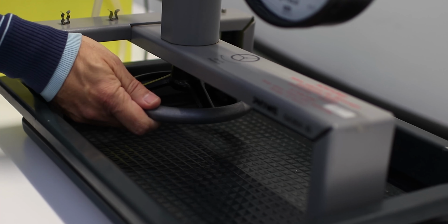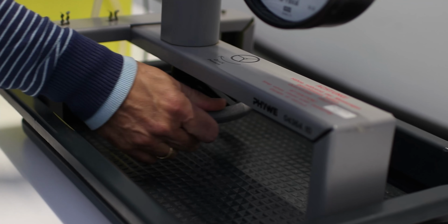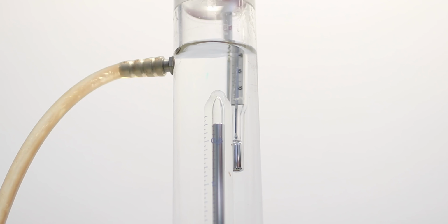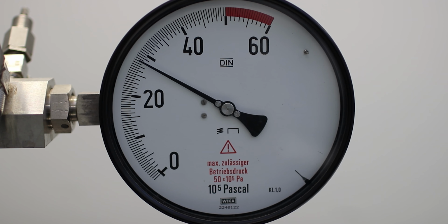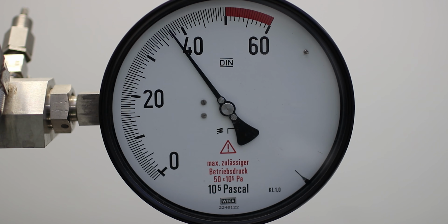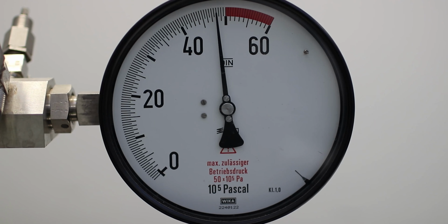A further reduction of the volume needs more effort in order to turn the wheel. We observe that the volume is barely reduced, while pressure rapidly increases. We can observe that the liquid bears high pressure values without a perceptible change in volume. In fact, the safety limit in pressure is easily achieved.